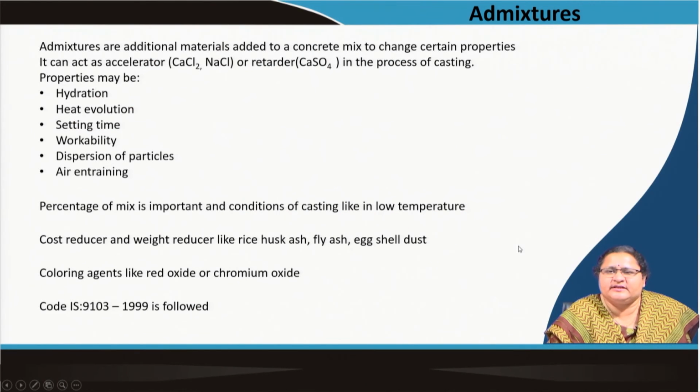Next we come to admixtures. What are admixtures? They are added additionally to the mix and they change the properties. What properties? It can act as an accelerator, it can act as a retarder, or else it can be used as a cost reducer, weight reducer, giving insulation properties.